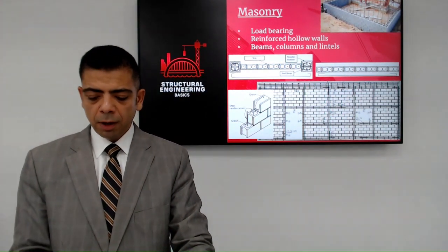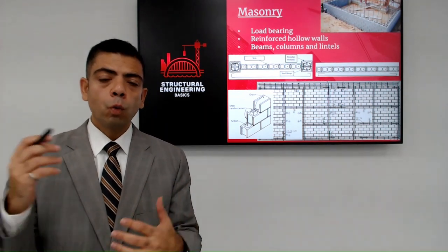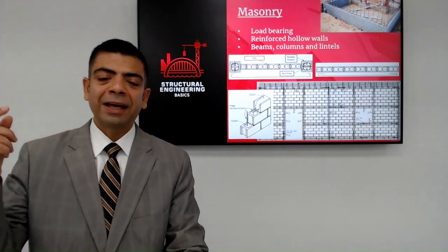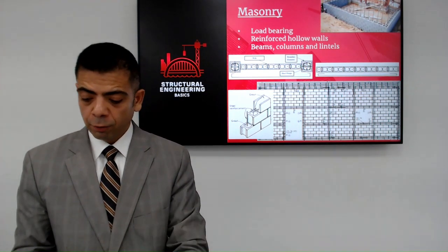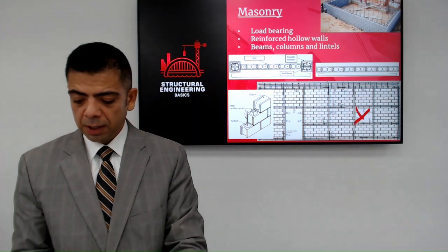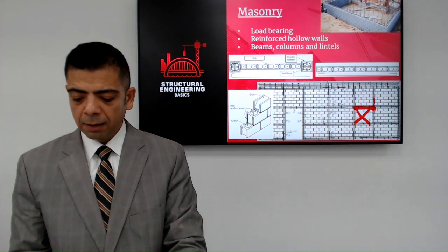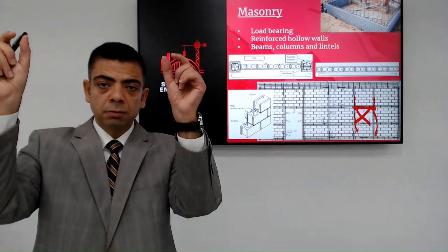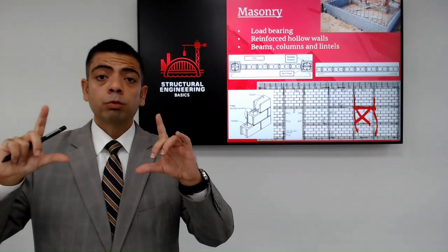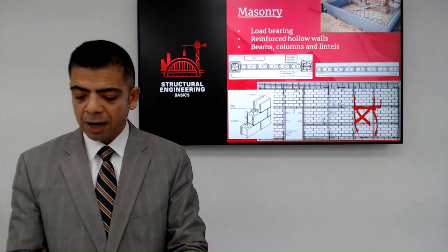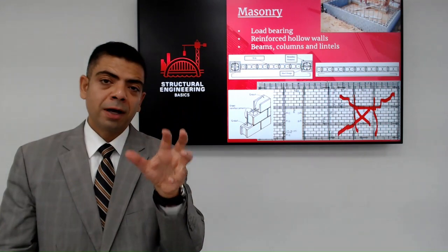This is an example of how you can build structural elements like beams and columns within a given wall. This will give a clear path for the load and reinforce openings. So for example, this is a window, and typically it would need a lintel or a beam above it, and introducing these reinforced columns or grouted voids around it will reinforce the opening against any cracks that might result at this weak spot in the wall.